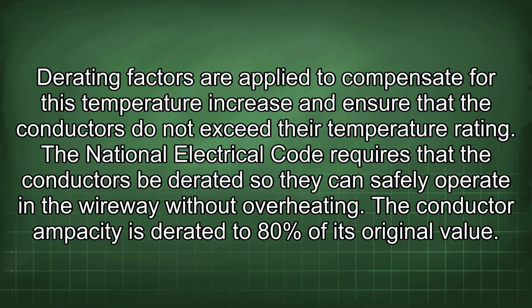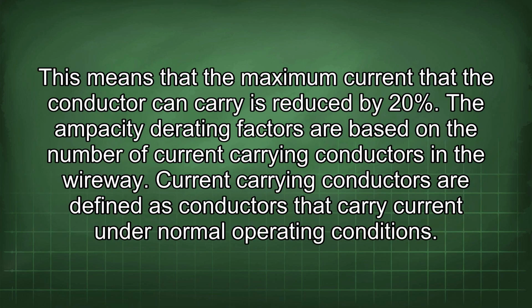Derating factors are applied to compensate for this temperature increase and ensure that the conductors do not exceed the temperature rating. The National Electrical Code requires that the conductors be derated so they can safely operate in the wireway without overheating. The conductor ampacity is derated to 80% of its original value. This means that the maximum current that the conductor can carry is reduced by 20%.